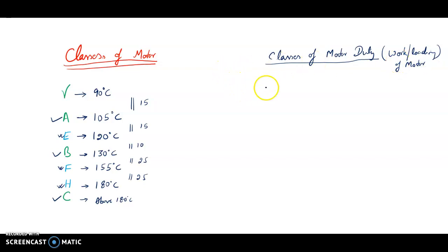So one is short time duty. The motor is running for a very short time. Examples are a machine tool for position control, opening of doors, and some household appliances. These work for a very short duty. So we can classify it as a load which works for just a short time, then stays idle for a long, enough time. We will discuss all this.